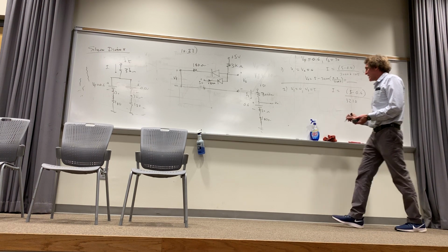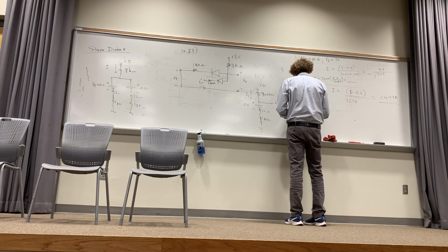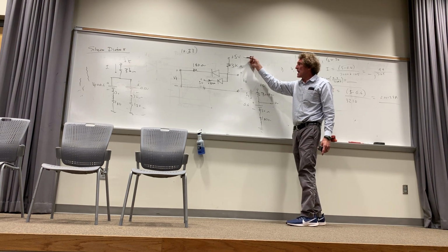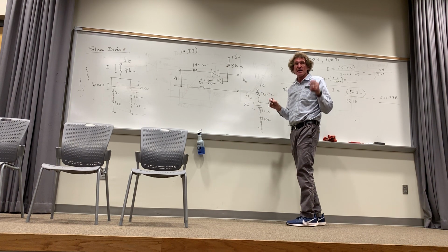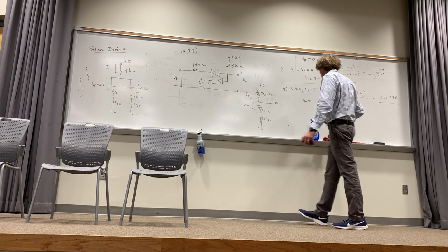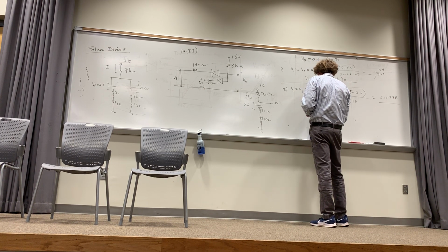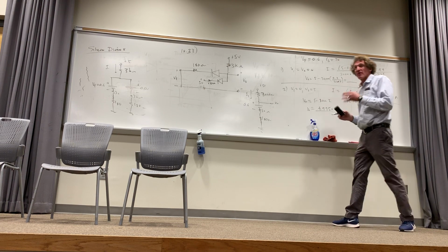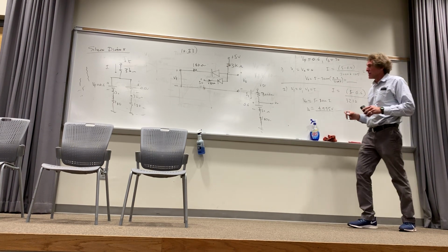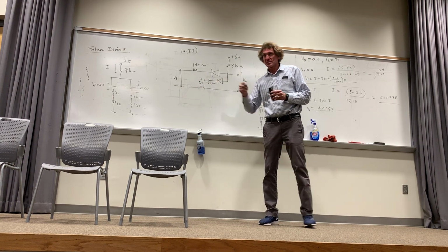All right. Now, what's the output voltage going to be? Just take a look at it. It would be 5 minus 3,000 times that current, right? Because that's the voltage drop here. The rest of the voltage has to go to ground. You all see that? Give me a show of hands if you do. So now I can say the output voltage is 5 minus 3,000 times that I. You want to tell me what that is, sir? 4.995. About 5 volts. One thing you're going to be taught on this one: if these are close to the peak value of voltage in the circuit, the output voltage will be about this voltage.